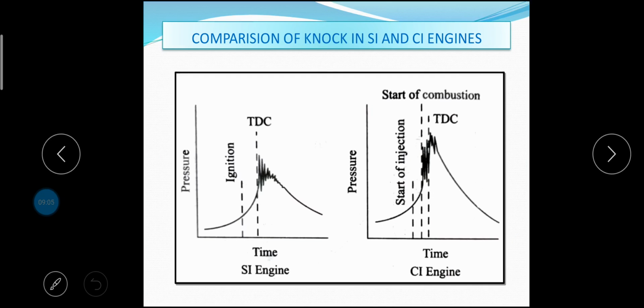It may be interesting to note that knocking in SI engines and CI engines is fundamentally due to the auto ignition of the fuel air mixture. In both cases, the knocking depends on the auto ignition lag of the fuel air mixture, but careful examination of the knocking phenomena in spark ignition and compression ignition engines reveals the following differences.